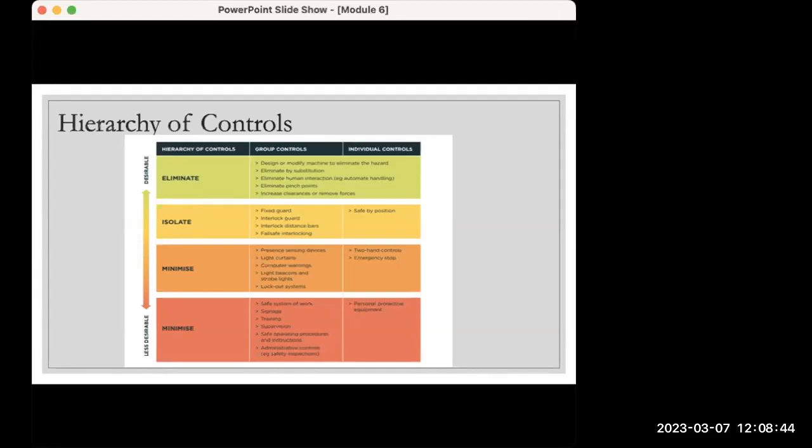In determining what type of guard to use, this should be considered as part of a risk assessment. And the most important selection criteria around that risk assessment process is understanding the probability and foreseeable severity of any injury, the intended use of the machine, the hazards present at the machine, and the nature and frequency of access by people in the modes including pre-start, operational, post-operational, maintenance and cleaning.